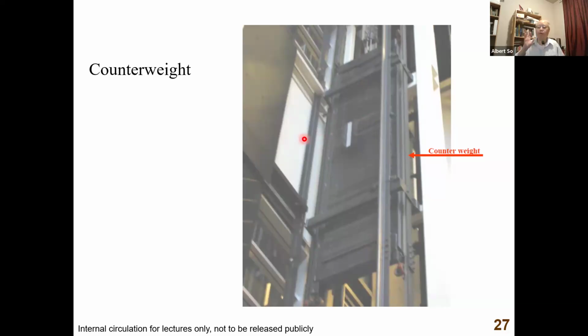And remember, most of the time, counterweight is set at the weight equal to the weight of the empty car plus half the passenger weight, but not necessarily half. Sometimes 45%, or even down to 40%. But seldom beyond 50%. Okay, why? When we talk about traffic analysis, I'll tell you why the counterweight is usually set to 45%, not 50%. Okay, but 50% is the norm.